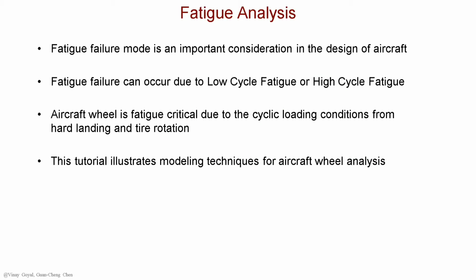Fatigue is induced by cyclic loading conditions and is an important consideration in the design of aircraft designs. So if the load is varying and there's fluctuations in the load, the repetitive loading condition will cause something called fatigue failure. And it could be induced by low cycle fatigue or high cycle fatigue.